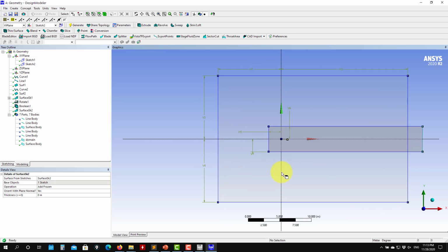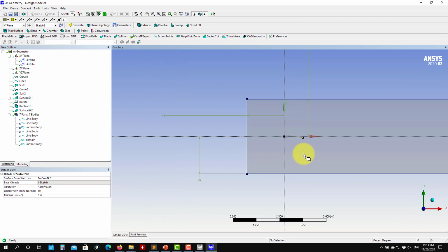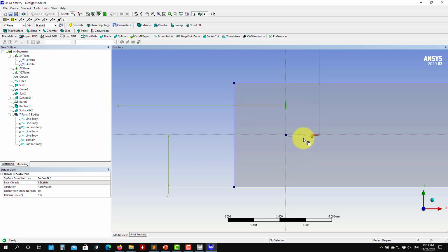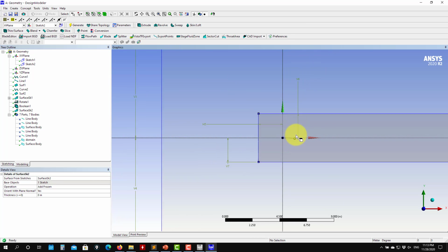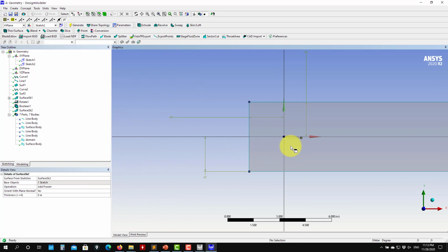Usually you have probably seen circular domains or C-type domains. That is when you decide to do that, but I like to work like this. There is no difference. In some rare cases you need to do different geometries and take different considerations. I like to work like this. In my case, I always have the velocity aligned with the X direction, and then I rotate the geometry, but we have seen that everything is parametrical.